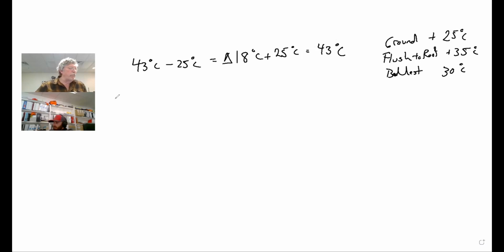So we'll use VMP. Before I do that, I'll do the temperature coefficient. So I'm going to take 43 degrees times 0.45% per degree Celsius, because that's the temperature coefficient when you start at VMP, and it's going to be 19.35.